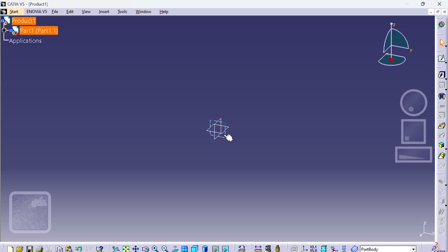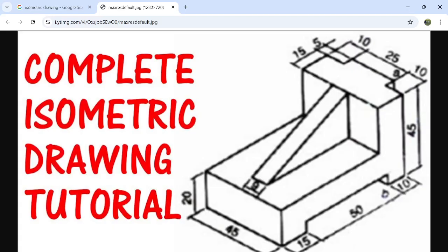If it is ZX, why do we require this? Because while drawing, as per the perspective you are using to draw, you have to select the plane. Suppose I draw a 2D sketch of this shape in this way, with the cursor moving. If I want to draw this, then I use the ZX plane.